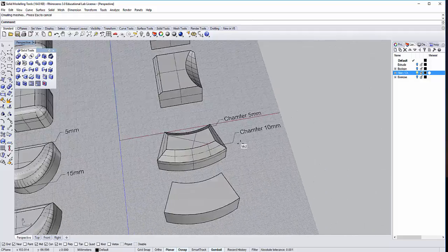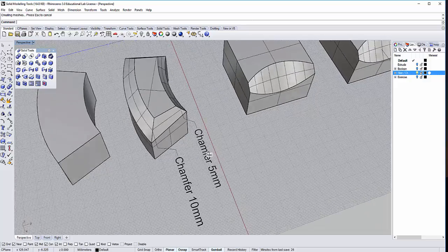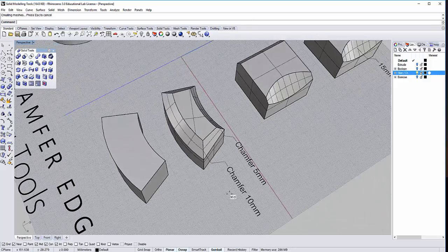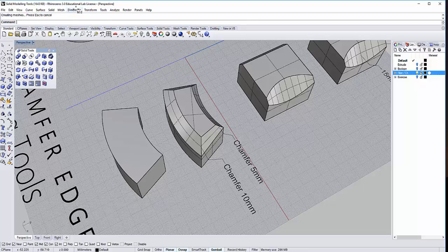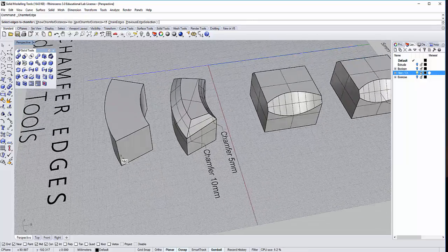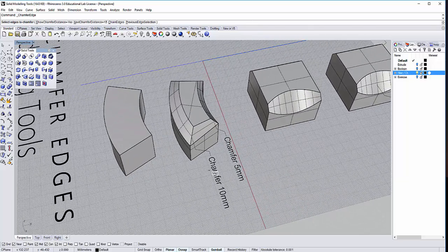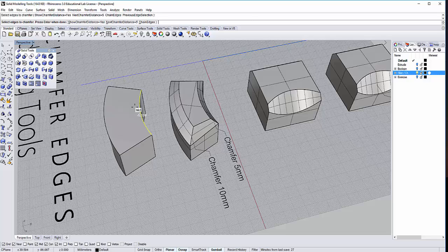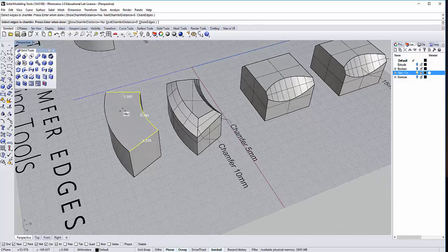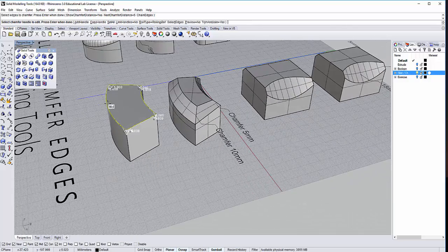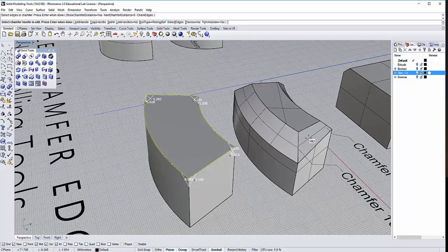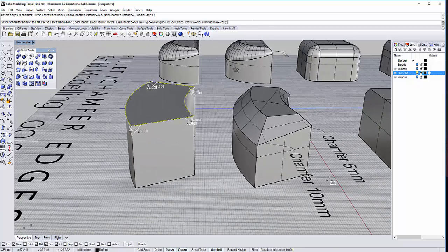Let's go back to here, the last one. Okay, notice it's chamfer 5, chamfer 10. What do I do? Go to your chamfer tool, which is this. It's 5, right? So input 5 first. Supposed to be the edges here. Drop it, drop it, drop it, enter. So let's say for example now it's at 5, we want a 10 here. What can we do here?